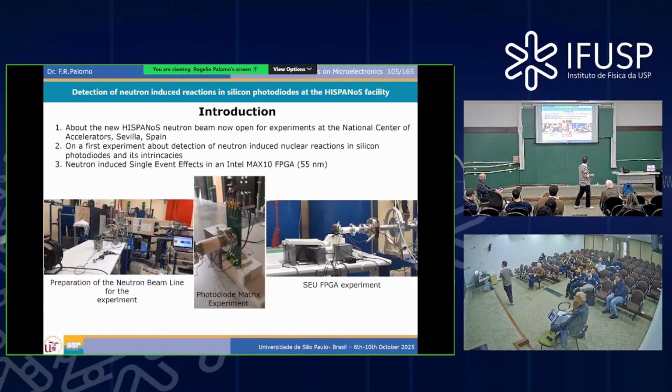An FPGA, field programmable gate array. It's a circuit full of digital resources for you to implement any digital design that can fit in. Okay, it's very typical. Nowadays, it's very rare to make full digital ASICs because FPGAs are by far cheaper. So if you are interested in a pure digital design, the first option is always an FPGA.